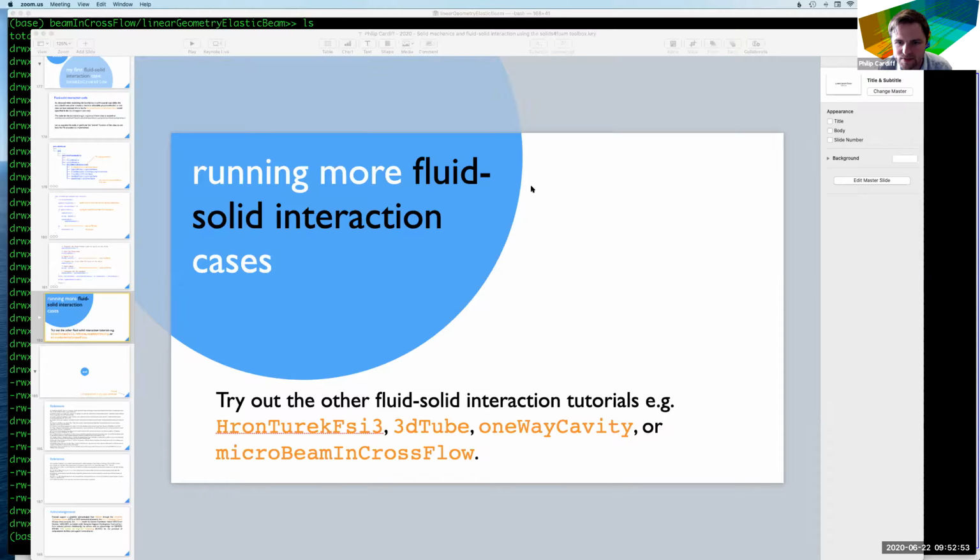Inconsistent patch and patch field types. Oh, sorry, I just read the end of your comment. Patch and patch field types. Yes, actually, this is because OpenFOAM 19 requires a couple of small changes to the case to get it to run. There is a public branch called port OpenFOAM. I think you'll see commits in the last few weeks. I've added an extra line in the Allrun script which will fix this error. I'd hoped to have it merged by today's training, but I didn't have time. So that will fix it. Sorry for that.